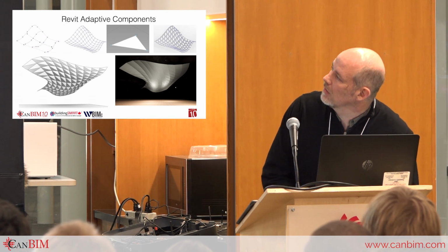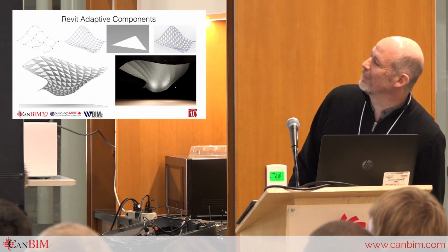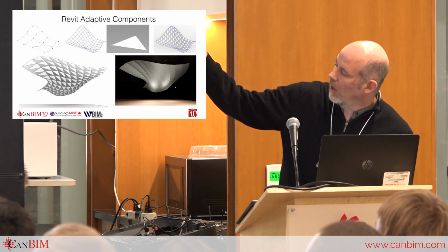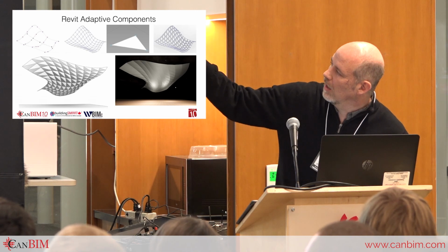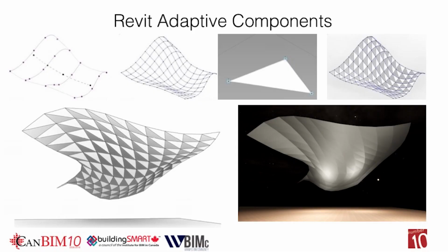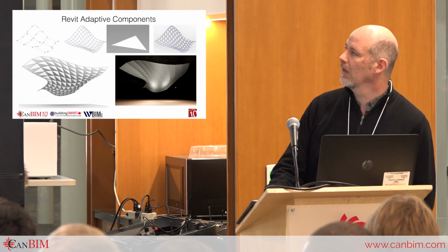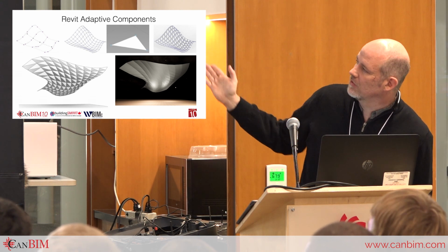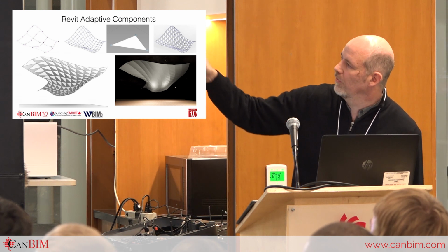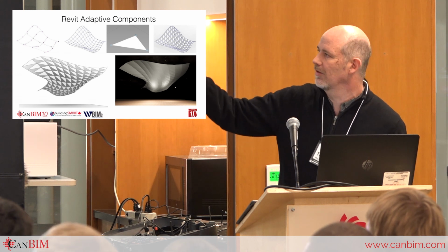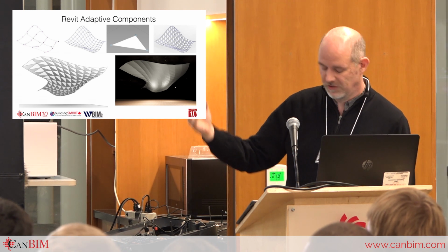So initially, okay, it's readable. On this image on the left, there are 4 arcs that are joined together, and they are on separate work planes. Those come joined together and create a plane of a curvy form, basically. After creating the plane, you can take that shape and then just divide it up in even numbers. So at each of those intersections, it creates a point. This is, I think, 10 by 10 space, but you can change whatever you want to. So it just literally splits it up.